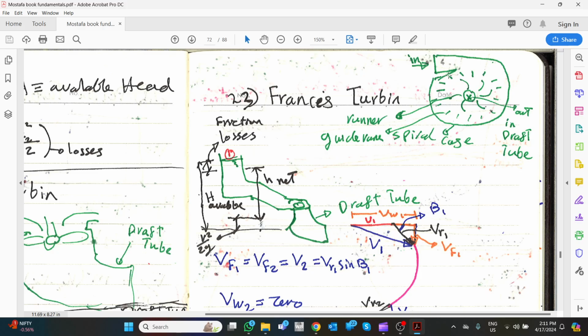So the velocity increases. Then the velocity will have a very high speed. So you're converting the pressure by reducing the gap to make more velocity. Then if you can see, the guiding vanes start to push the water here, then the water will rotate that impeller, then it goes out from the middle. This is how it is running, and this is how it is built.